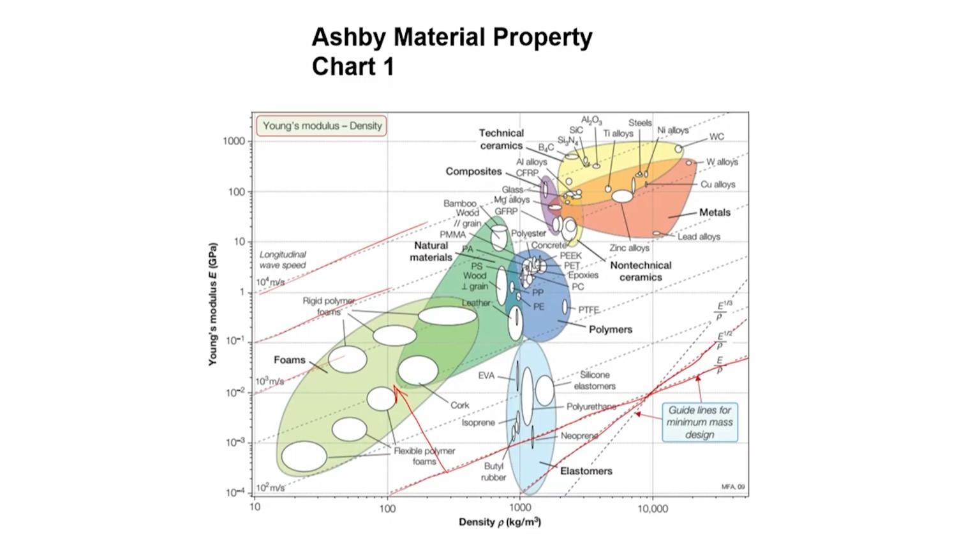So, suppose my cutoff level in this case is 1 GPa, so that in no way can I have a probe whose modulus of elasticity is less than 1 GPa. Then this is the line that we have to see, and then along this line I have to see which materials are coming up above it, like CFRP, like Si3N4, some titanium alloys, though they are mostly here.